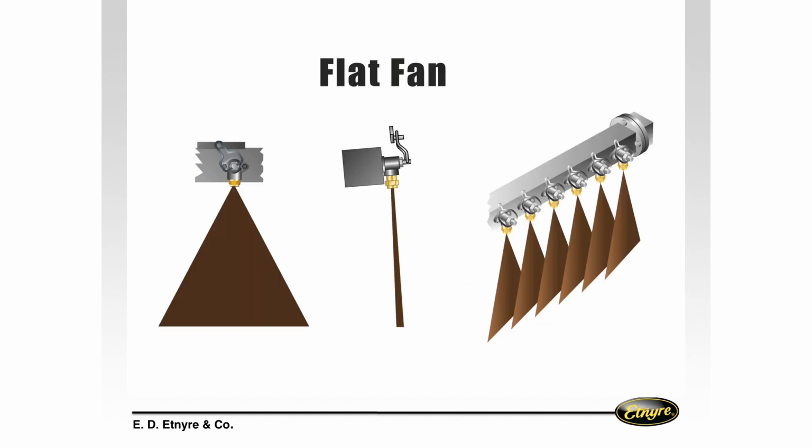So we want a flat fan, we call it. So if we have those two things right, if our nozzle's set correctly, we're 12 inches from the ground to the bottom of our nozzles, they're set at 30 degrees, we get a good flat fan that doesn't touch everything, and it'll look like you put that tack down with a paintbrush because it just lays it right on out.